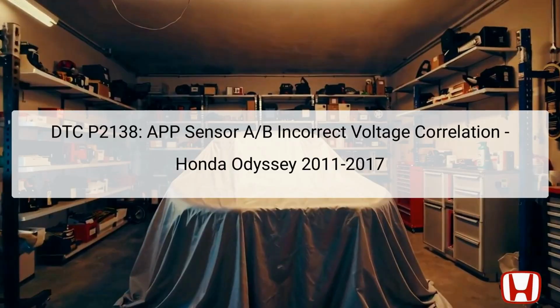The Diagnostic Trouble Code DTC P2138 indicates an issue with the Accelerator Pedal Position (APP) sensor in your Honda Odyssey. Specifically, this code refers to a discrepancy between the readings from APP sensor A and APP sensor B. Each APP sensor is responsible for sending voltage signals to the Powertrain Control Module, PCM, regarding the position of the accelerator pedal. These readings help manage the engine's fuel and air intake, ensuring optimal performance and responsiveness.